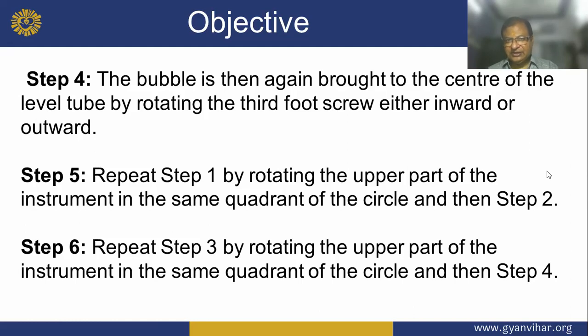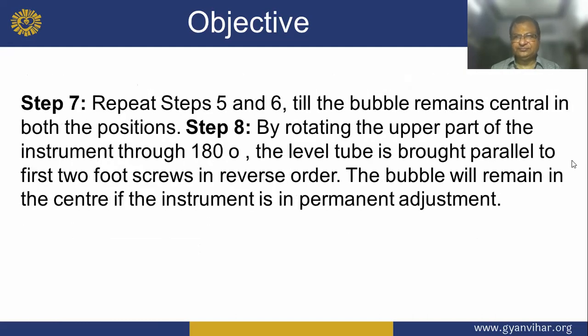And next, repeat step 3, rotating the upper part of the instrument in the same quadrant of the circle. And then step 4, repeat steps 5 and 6 till the bubble remains central in both positions.